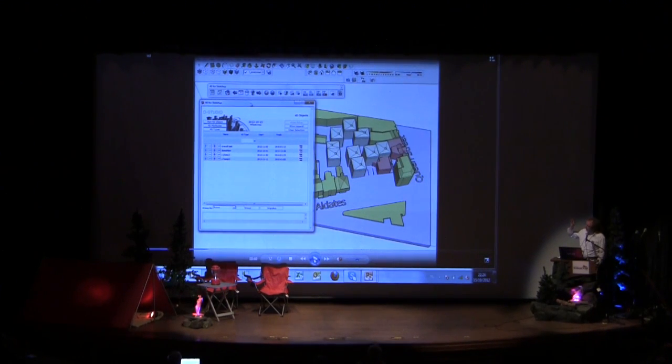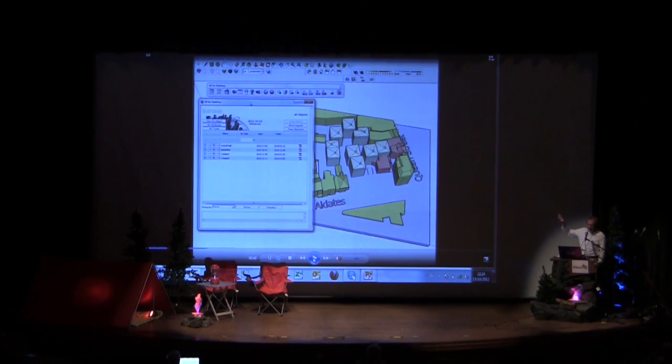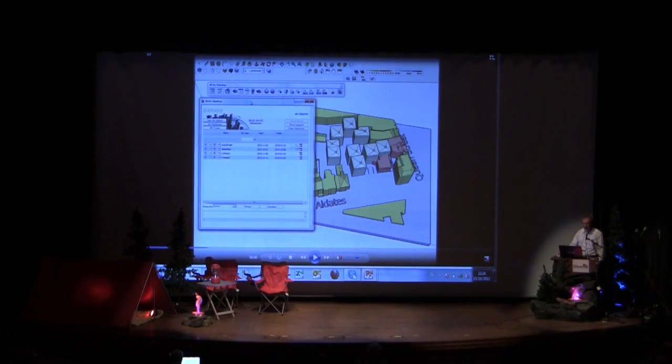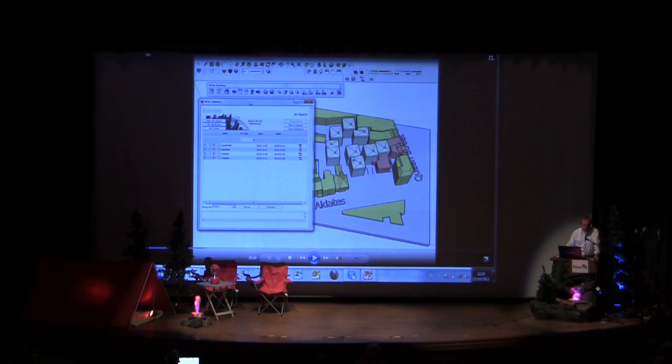Now what you see is we haven't imported it, we linked it together. I can't show you that on the movie, but if you modify something in the MS Project file, you can immediately see the results in the 4D model, which we're going to construct now. So we have a series of XD objects with a start and an end date, and eventually also other kinds of attributes or parameters which are defined in MS Project.